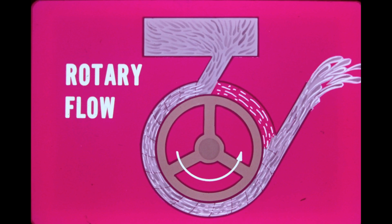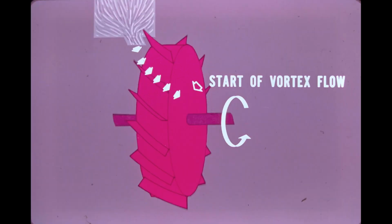Now, what about vortex flow? Let's look at vortex flow a step at a time. This water wheel has blades which are curved to perform two functions. One function, of course, is to provide a surface for the water to push against to make the wheel rotate. Once the wheel is rotating, centrifugal force throws the water from the wheel. The second function of the blades, then, is to channel the flow of water from the wheel. In this example, the water is channeled off the right side. This side flow is the beginning of vortex flow.